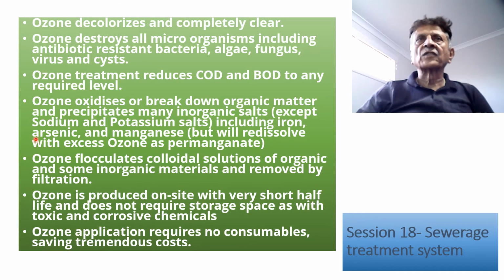The advantages of application for ozone are as follows. As I did explain to you, it decolorizes and the water will be clear. It destroys all the microorganisms, bacteria, algae, fungus, and various virus and cysts. Ozone treatment reduces COD, BOD. Ozone oxidizes, breaks down organic material, precipitates the non-organic salts,